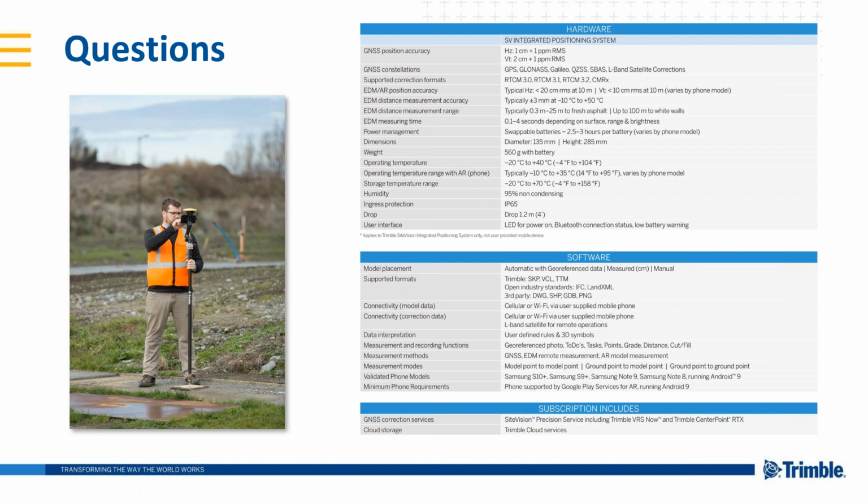And then when you bring the model out into the field at a future date and you're overlaying the model onto the ground, or if you've potholed and you're looking for that line to appear over the physical utility to that level of accuracy, you need to make sure that you've got GNSS corrections that are delivering that 2 to 3 centimeter accuracy, and you need to make sure that the coordinate systems and everything is set up correctly.